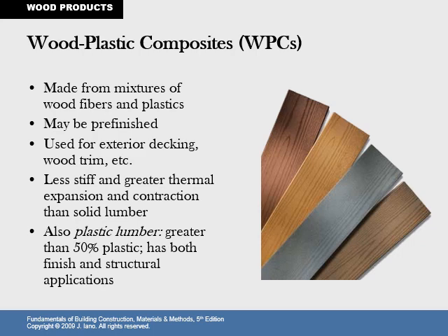A popular interior feature you have encountered, and something that's commonly used for flooring, is wood plastic composites, a new feature on the block. It's made of mixtures of wood fibers and plastics. It may be pre-finished, used for exterior decking, wood trim, etc. It's less stiff and has greater thermal expansion and contraction than solid lumber. Also, plastic lumber is greater than 50% plastic, and has both finish and structural applications.